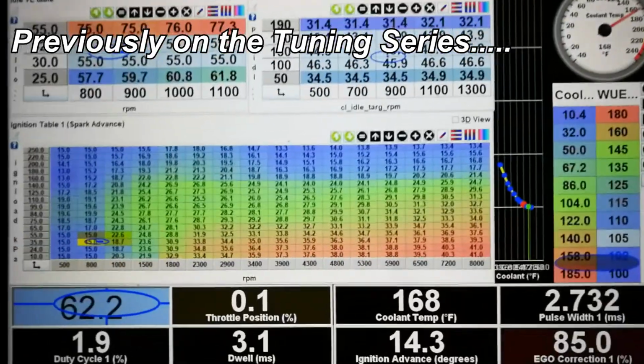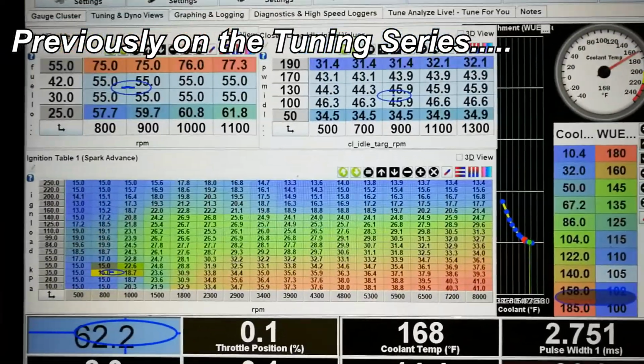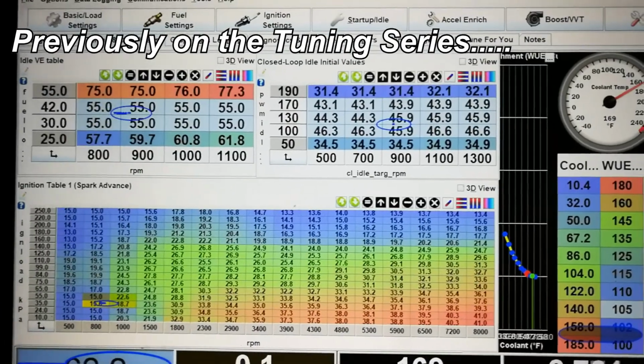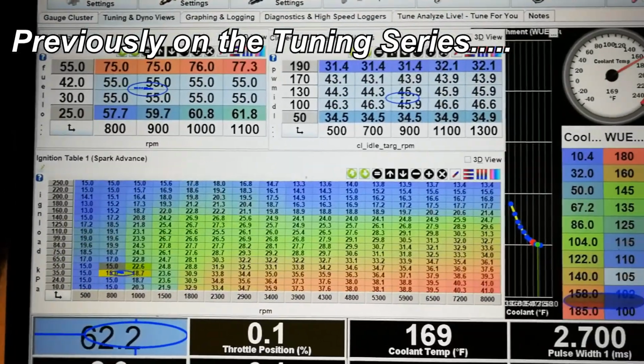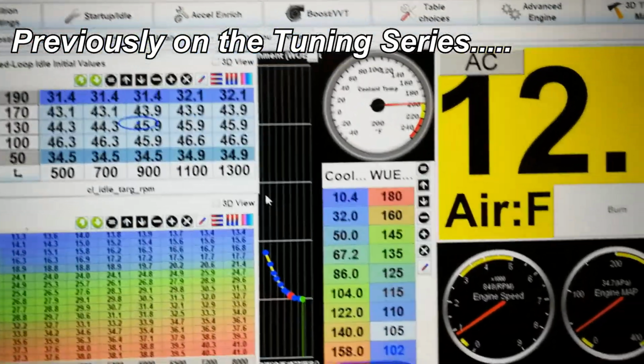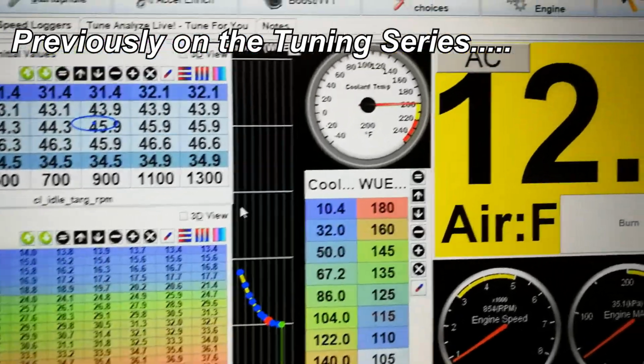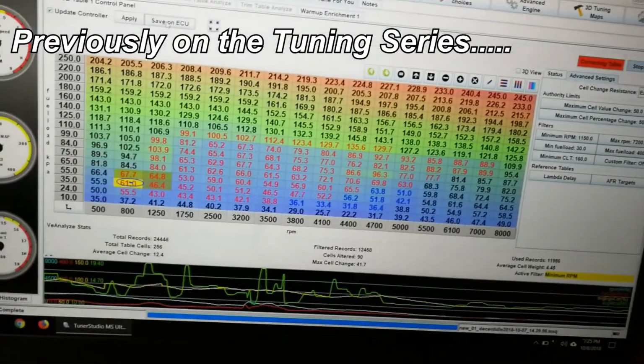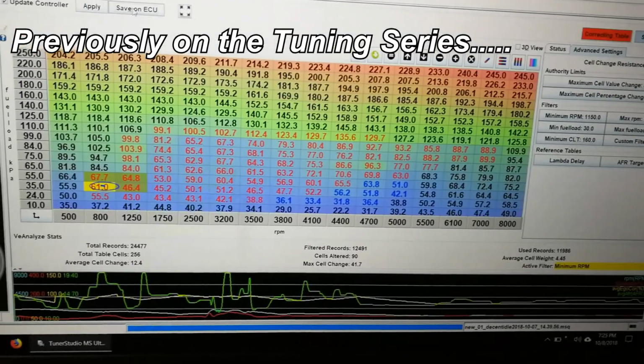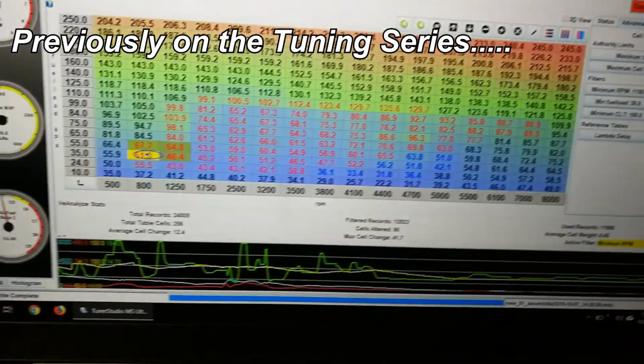Before diving into Tuner Studio, let's talk about our approach. To take full advantage, we need to change some things related to the fueling and the timing. There are many ways to do this, and this is where people get really confused. Fueling refers to not only your main fuel VE map, but also to cranking, warm-up, and accelerant enrichment, among others.